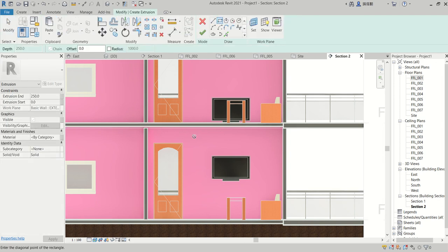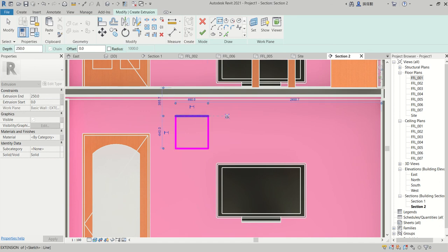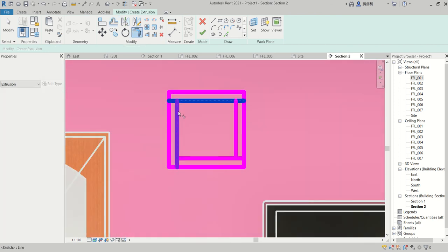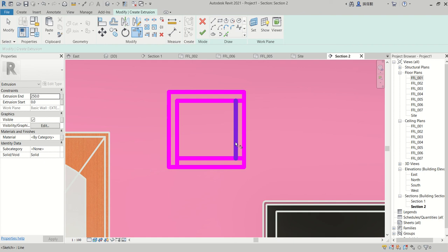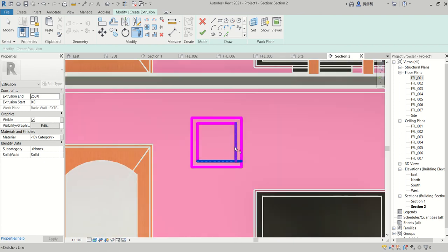Now I can create whatever shape I want to choose. So I'm drawing this. So I do offset to this. Offset. So let me say 2 inch. So for example, let it be like this. And as I said before, this pink line should not have any intersections. Let us trim it. This one, this one. You need to choose whatever you need. So the additional part will be automatically deleted.